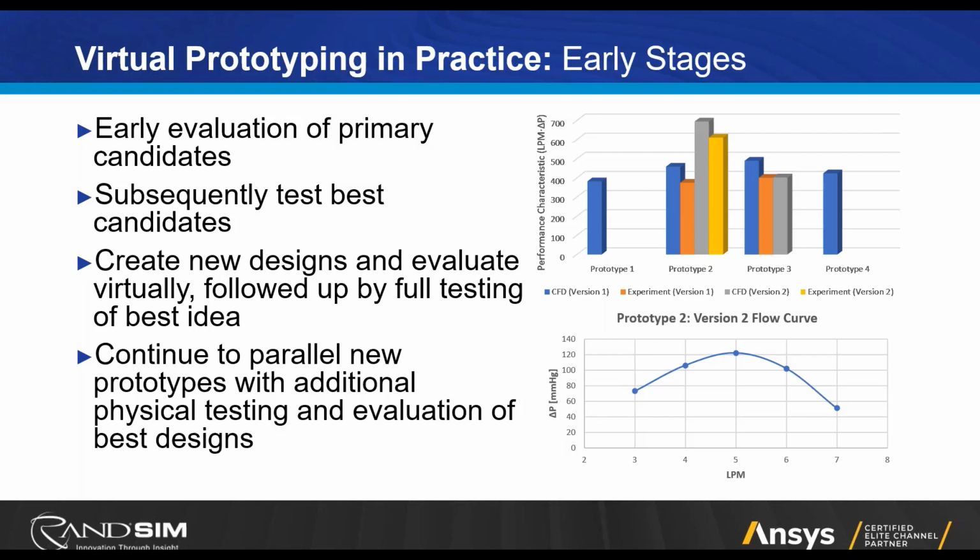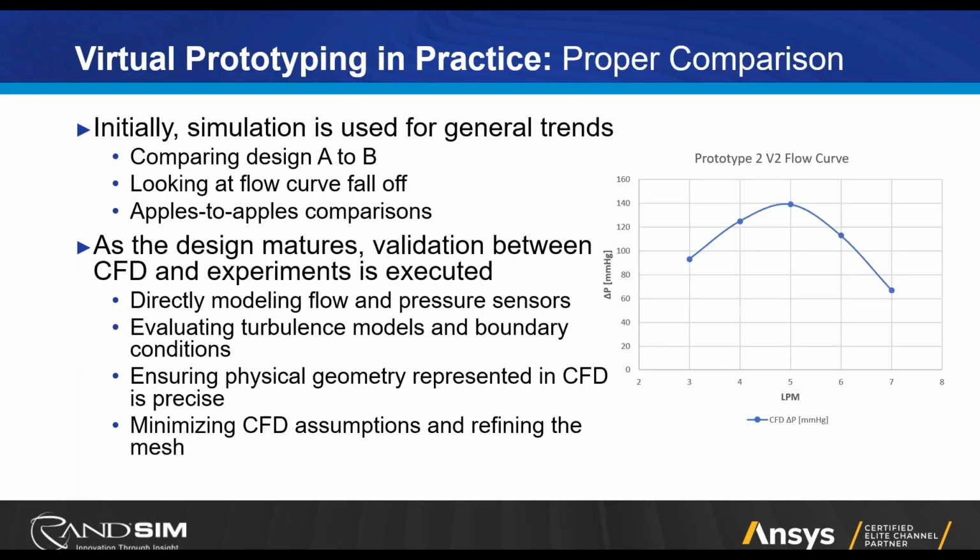on what your next best design might look like. So as you move from these early stages in the prototype development, where you're likely going to have a mismatch between your CFD and your experiment, one thing to always keep in mind is that just because a CFD analysis isn't predicting the absolute value of, let's say, your pressure drop, or your differential, I should say, for a pump, it does predict trends well. And that means that as long as you're doing what we would call an apples to apples comparison, it is going to be predicting performance relatively accurately. So here we can see that on the right side, I've indicated what a traditional CFD flow curve might look like.